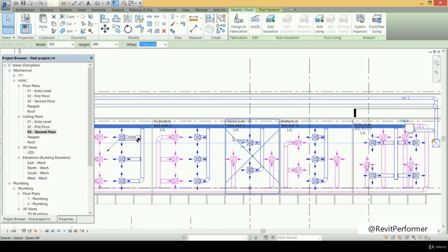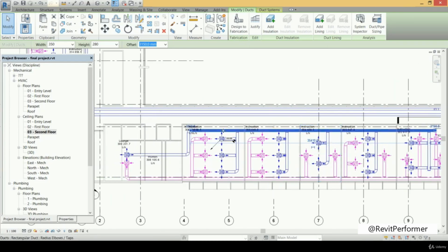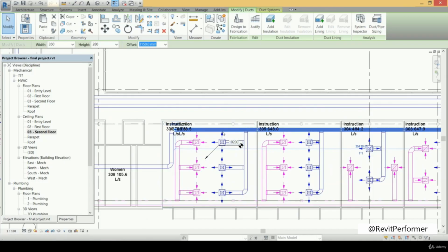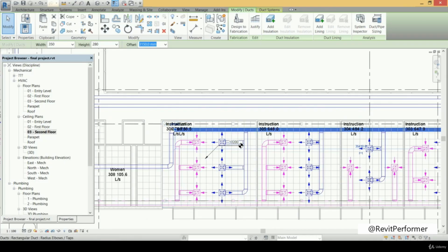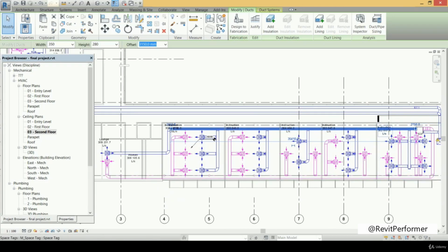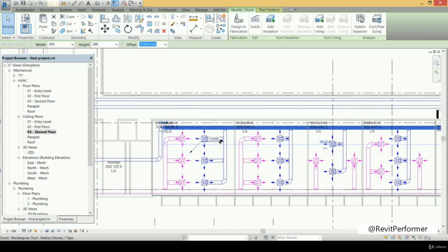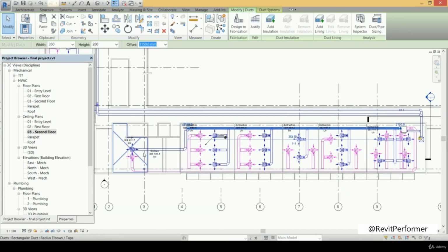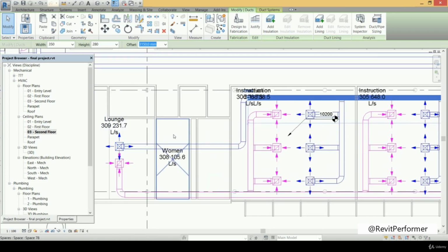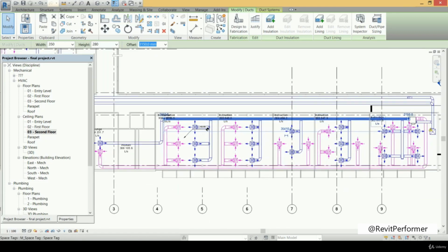And also the same thing, if we are talking about the airflow for the final part of that duct, for example, it will be smaller than the airflow of the first part. This is because the airflow of that part is only the airflow that will go through that diffuser, while the airflow for the first part is the total airflow that is going through that branch and that second one and that third one and that fourth one and so on.